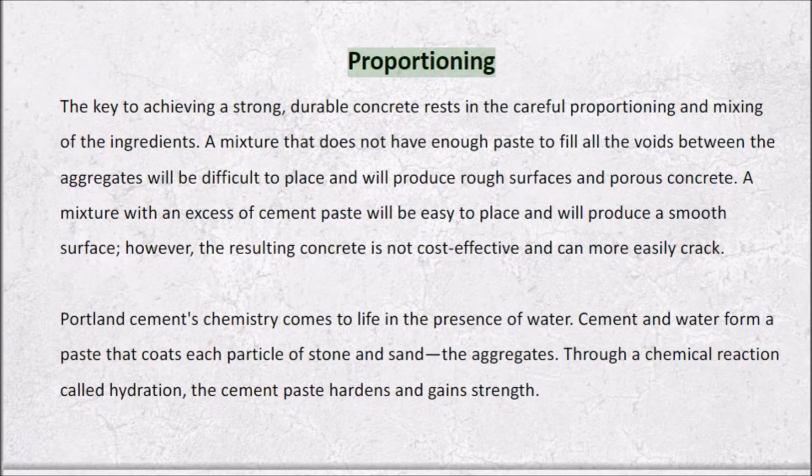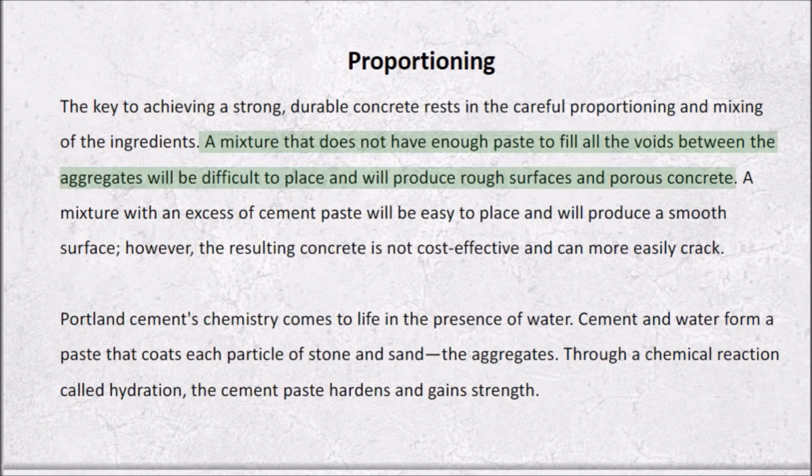Proportioning. The key to achieving a strong, durable concrete rests in the careful proportioning and mixing of the ingredients. A mixture that does not have enough paste to fill all the voids between the aggregates will be difficult to place and will produce rough surfaces and porous concrete.